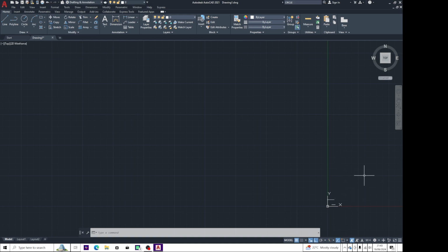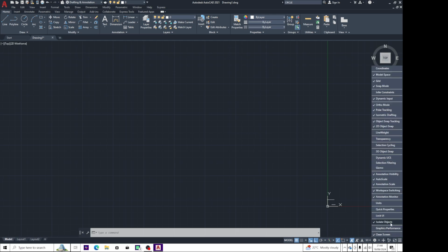One of the crucial tools that you need to tick, there are two. The most important one is the dynamic input, and if you need, you also check the units. Like these units, once you check them, you know that now we are doing metric. The dynamic input is also checked. I mean the dynamic input, not the dynamic UCS command.